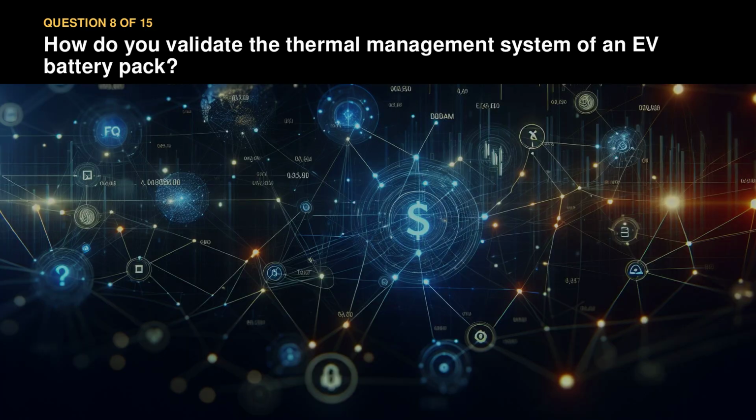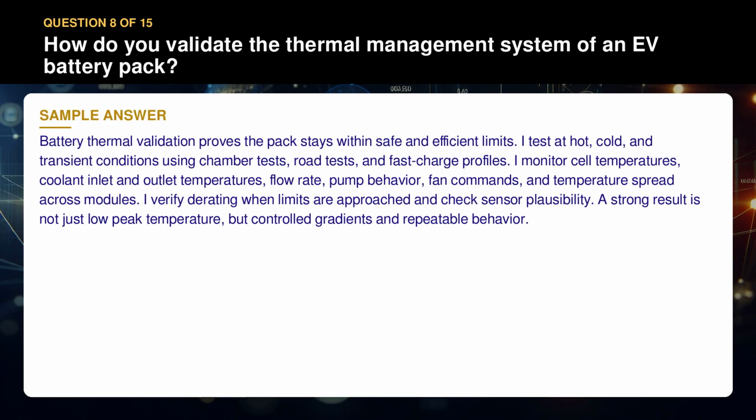Question 8. How do you validate the thermal management system of an EV battery pack? Battery thermal validation proves the pack stays within safe and efficient limits. I test at hot, cold, and transient conditions using chamber tests, road tests, and fast charge profiles. I monitor cell temperatures, coolant inlet and outlet temperatures, flow rate, pump behavior, fan commands, and temperature spread across modules.